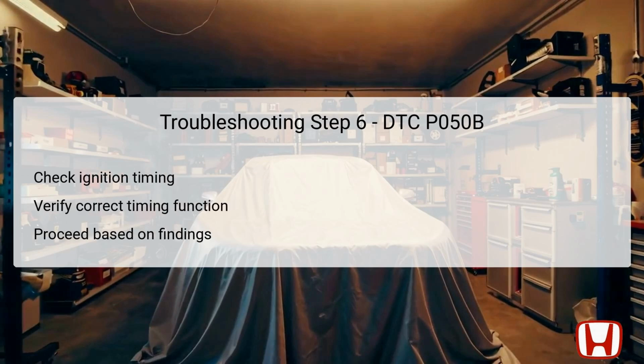In step 6, focus on determining the ignition timing of the engine. This step is vital, as proper ignition timing is crucial for efficient engine performance and smooth operation, especially during cold starts. If the ignition timing is confirmed to be within specifications, you will proceed to step 8.